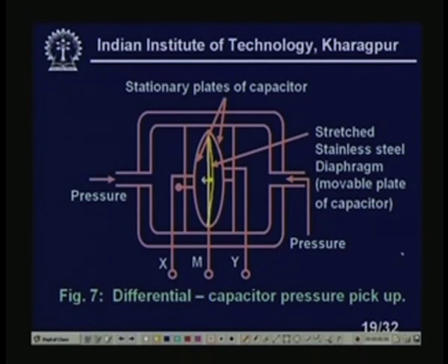Now, this type of pressure transducer, as a differential pressure transducer, has tremendous applications in modern-day instrumentation. You will find it everywhere, for example in flow sensors, which, as you know, are huge in number in the process industry. In all flow measurements, especially in the case of orifice meters, Venturi meters and pitot tubes, we use some differential pressure pickup, because this output is to be transmitted to the control room. So, I need this differential tapping. It looks like this in flow measurements.